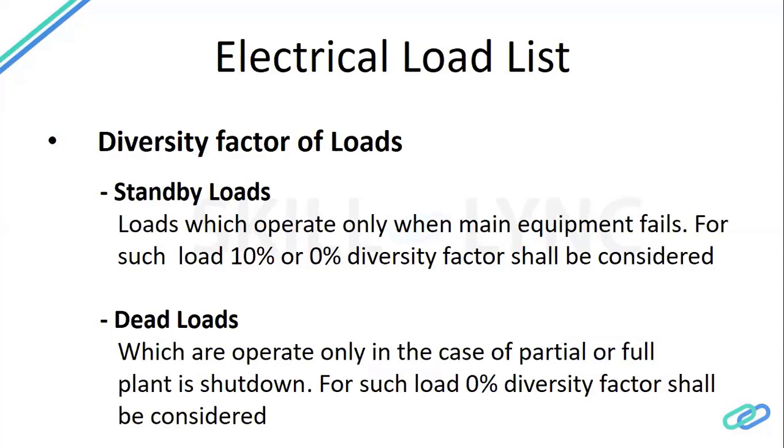A fire pump will only operate in the case of fire, and in the case of fire, obviously the other loads will shut down. The same goes for the welding socket. Welding will happen in the plant only when the plant is fully or partially shut down. So it will not put a burden on the transformer. So you don't need to consider these dead loads on the transformer. Otherwise, the transformer will be very oversized.